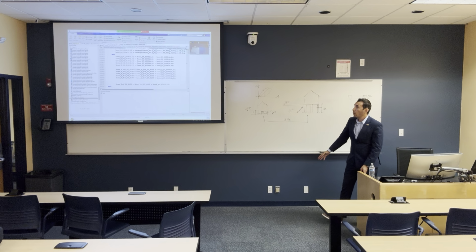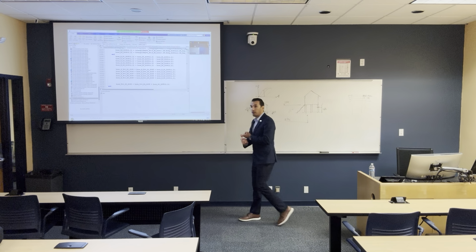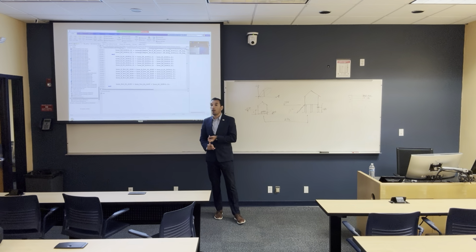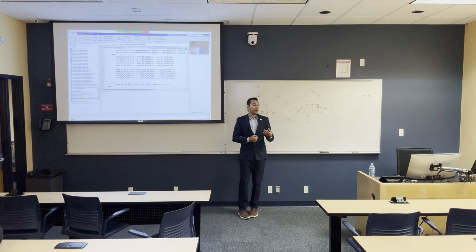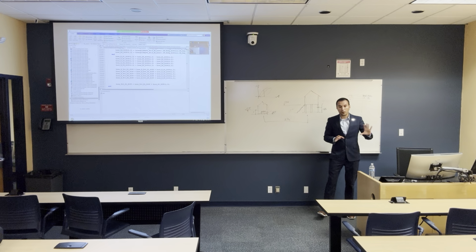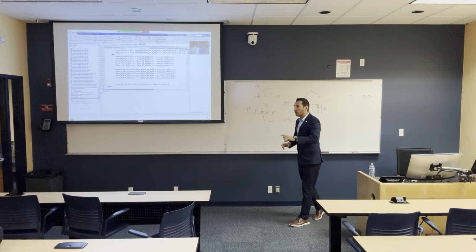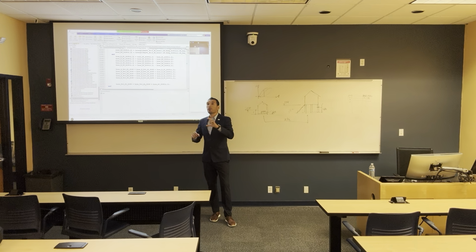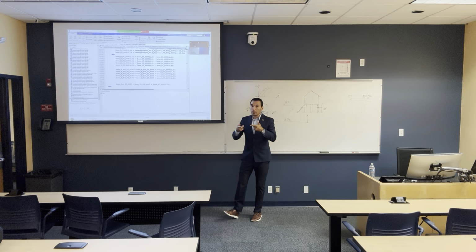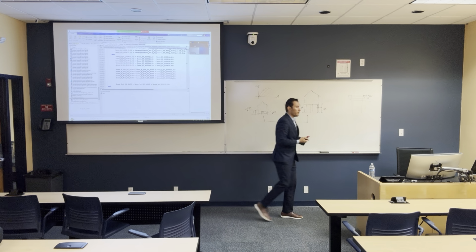So for now, we have only investigated flood barriers and water pumps. I talked briefly about elevating the water sensitive components. If you saw the Excel files that I gave you, for the 3D, you will find an Excel file that says fragility band, and there's one that has EC. EC means that's a new fragility if we elevated the water sensitive components.